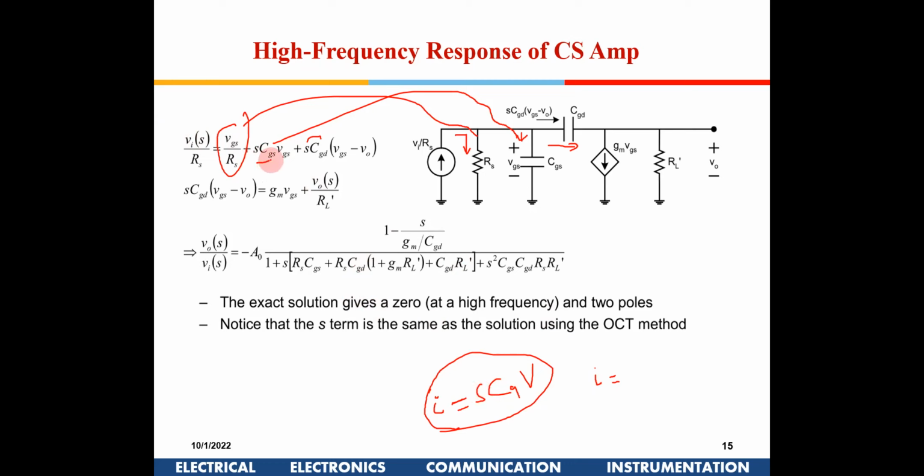So now, these are the currents. You write these three currents, three equations, right? And also we have V0 as gm into RL dash, right? So V0 also you substitute as gm into RL. So again, all these things get cancelled, and you have this gain equation coming.